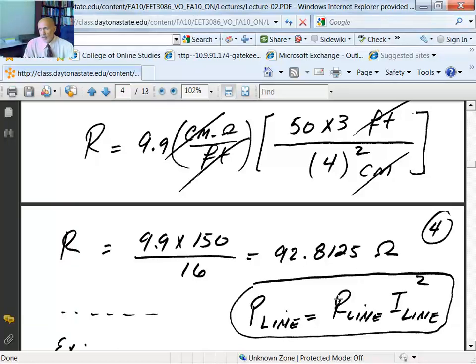And if you notice in big distribution, the power company jacks up the voltage to about 765,000 volts, because when you jack up the voltage, the current goes down in the power transformer, and that's just to minimize the transmission losses. The power company doesn't charge the customers for the power lost on the line. They have a meter right at your house, so everything lost on the line between the power company and the residence is the power company's responsibility, and so they need to minimize that.